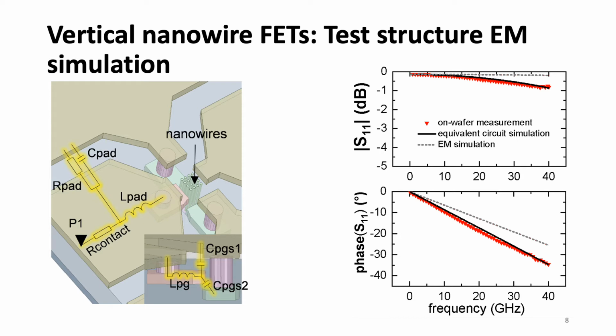To take into account the 3D interconnects, we used the ADS Momentum EM simulator to model an open structure up to the transistor's terminals. The obtained S-parameters permitted to decorrelate the series and parallel components at different reference planes and to build a distributed electrical model from the pad to the gate and drain access.